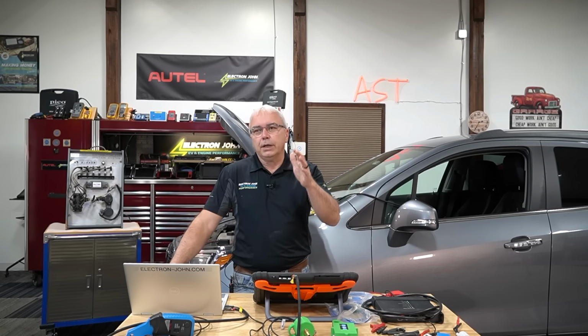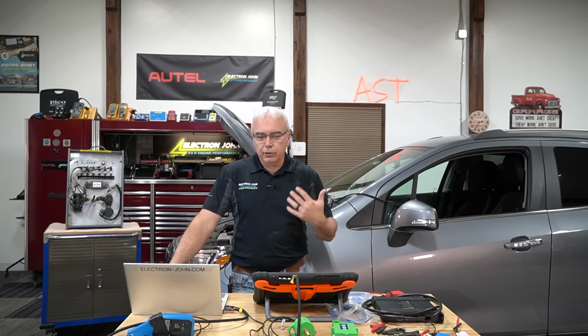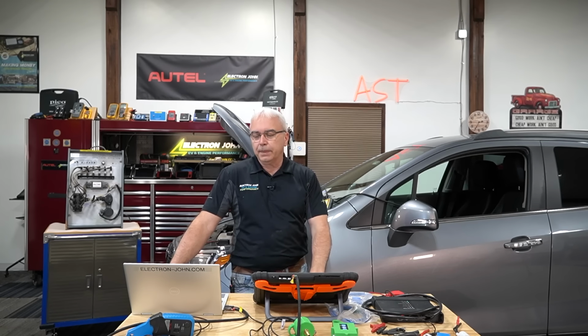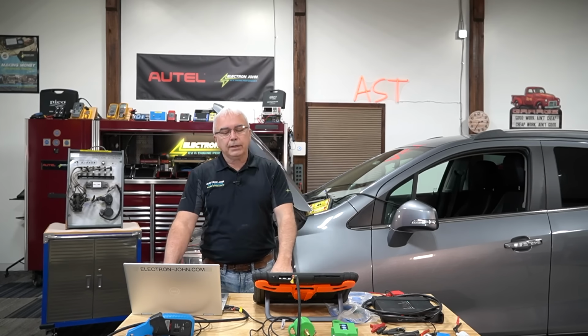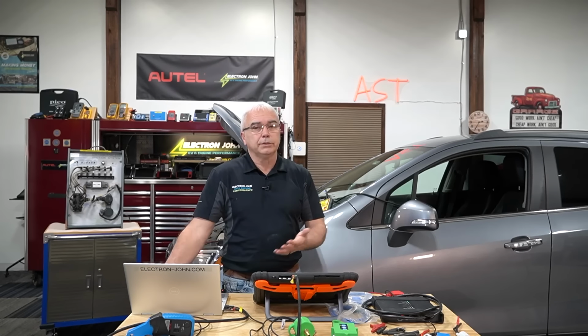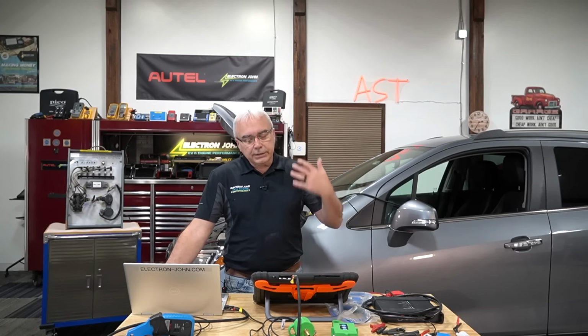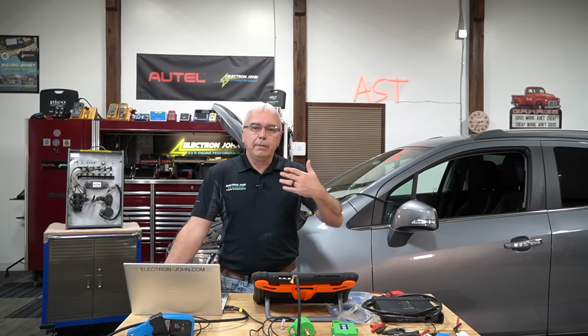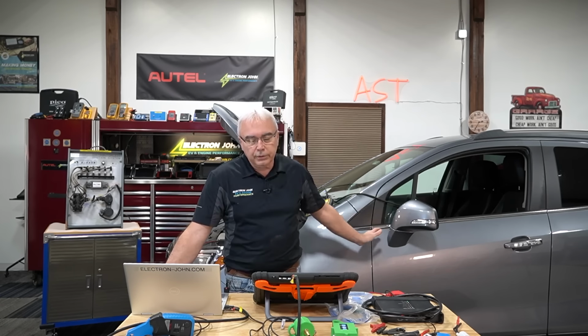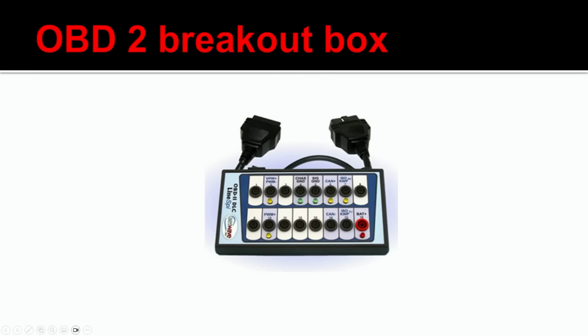But I just used all my human senses, and I put that in the back of my mind for future reference, right? Because I had no communication with my scan tool, and that's one of my go-to tools, as we said earlier, that made me say, okay, let me check the data bus network. So I hooked up my OBD2 breakout box, and I tried to get a waveform.